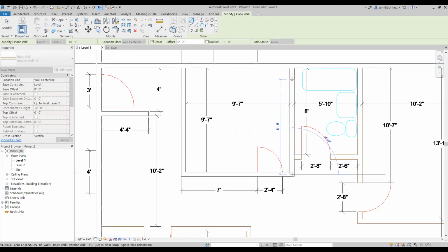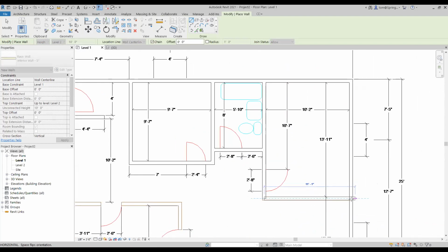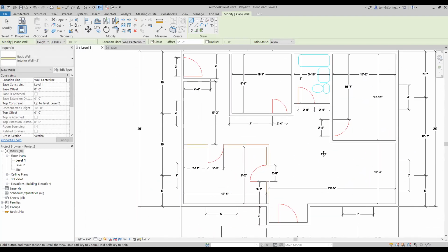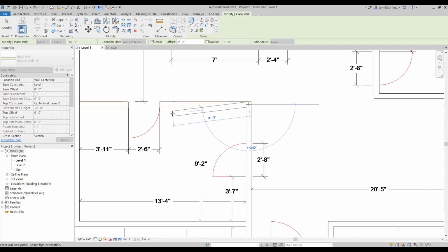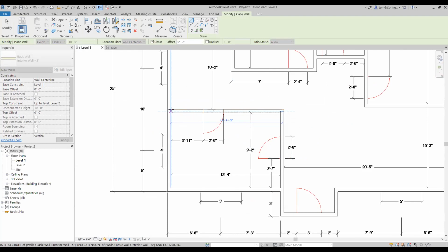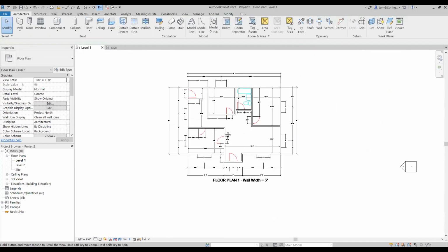And what I'm doing right here is I'm drawing my center lines with cool aplomb, as they say. And I'm gonna continue on through here, and then down to here. Okay, and then here I'm going to pick up this line and pull it down. And you'll notice it's picking up the center lines because when you start with an AutoCAD plan, it does that for you, which is pretty cool. And so I'm just going to continue on here using this. And we'll go ahead and pick here, and there. And we'll go all the way across. And that is how we put in the walls, okay? So that makes life a lot easier.